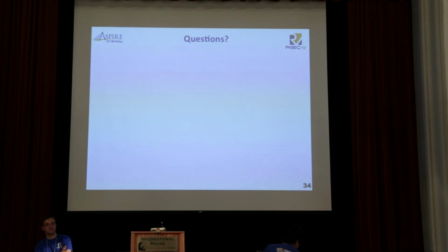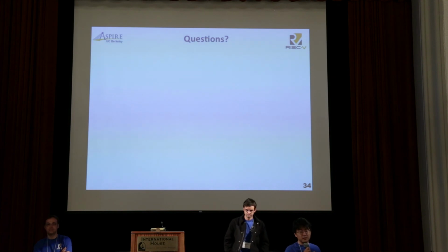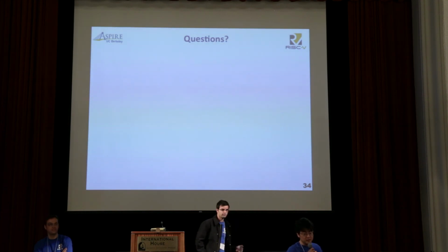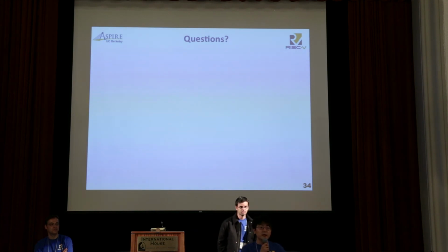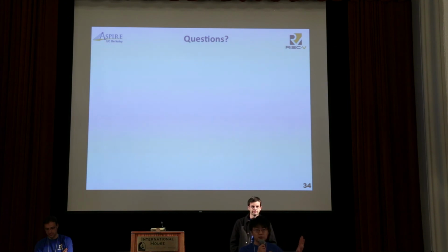Yeah, so there's a little bit more consideration you need to do if you want to integrate the V extension in an out-of-order processor. Like, are you going to rename the vector registers? How does predication all work out and things like that? We definitely had discussions about it. And Hwacha is more suited to pushing in-order designs to their limit. So I think if you want a high-performance out-of-order V extension, it would need some more architecting and microarchitecting, but we can definitely talk about that. I mean, we've been talking about that for years.